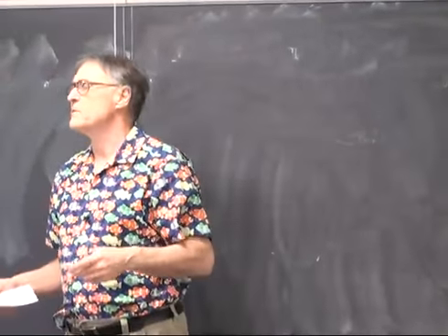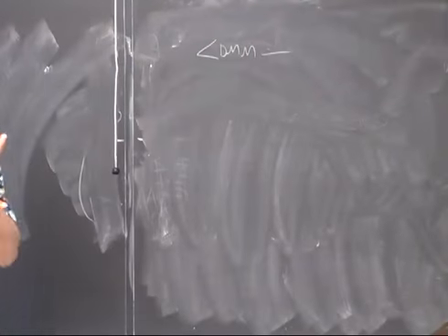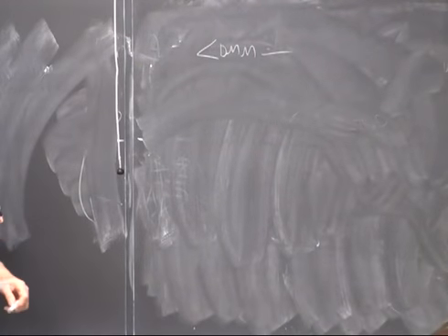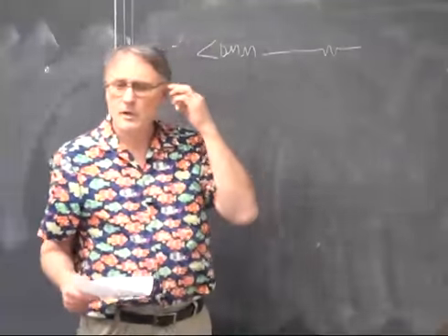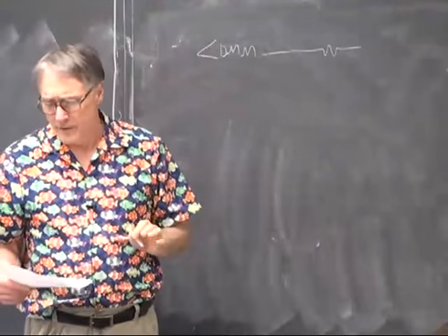So the specific circuitry we're going to use for the digital multimeter is a digital multimeter probe. This is the probe you use to hook to the device under test. Before we go into the ADC, we're going to add some protection.